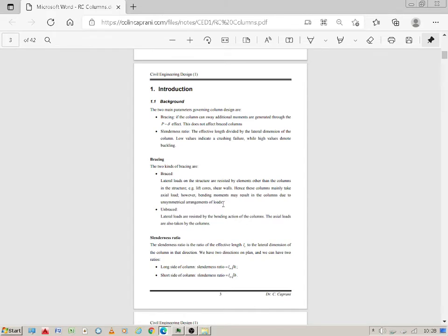And the key thing you've got to remember is that with reinforced concrete, basically all the joints are fixed, whereas in steel, basically everything's simply supported. You've got moment maybe from eccentricity of loading at the load point when you've got a fin plate, but basically these connections are all fixed. So when you look at analysis, you're looking at fixed columns. The beam is fixed at the column. But in this video, we're not looking at the analysis yet, we're just looking at the actual design of the section.